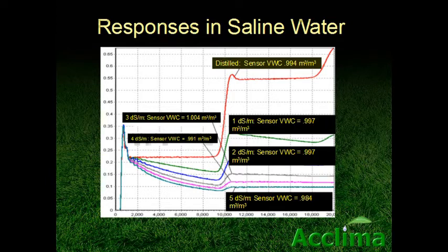As we add salt to the water, we can see a drooping attenuation of the incident wave and the associated attenuation of the reflected wave. If we were dependent upon waveform amplitudes rather than timing, we would be in serious error trouble. Note that in these saltier solutions, the time of occurrence of the reflected wave is becoming difficult to see with the naked eye. But there is an inflection point associated with the reflected wave that can be accurately recovered from all these waveforms using appropriate digital signal processing algorithms.